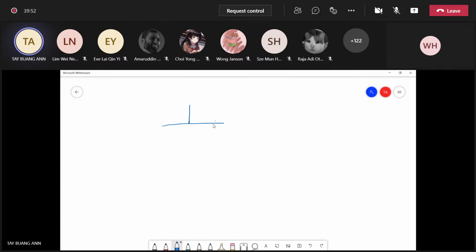Even if you apply 15 Newton with a very blunt object, it will not go through, because the effect of this 15 Newton is distributed over a large area, so the effect becomes very small. Instead, if you use a needle with a very small area, the effect becomes very large, tremendous. That effect, we use pressure to describe. That is why it is necessary to talk about pressure instead of force. The force cannot explain this.